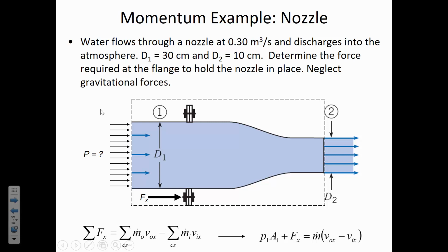It's only imaginary in the sense that where you choose to locate the control surface can change, but regardless of where you put it, there is pressure in that pipe, and it does affect the force that has to be applied. So the way we account for it is by putting the control surface and then just treating this pressure as though it's an external force on the left-hand side of the equation.